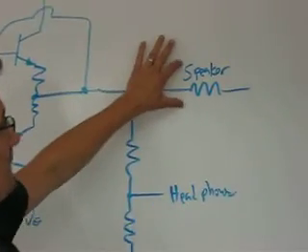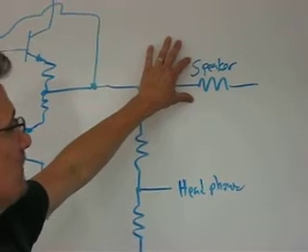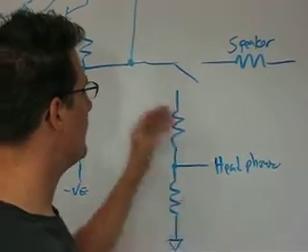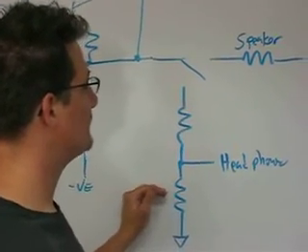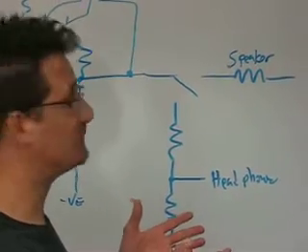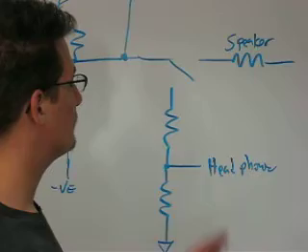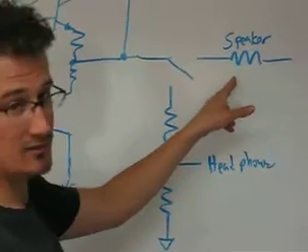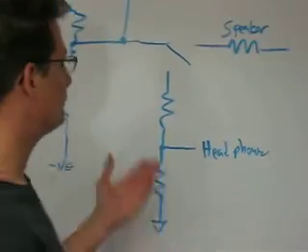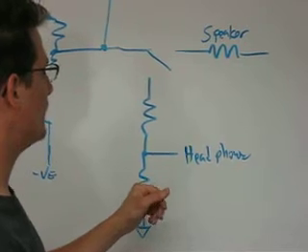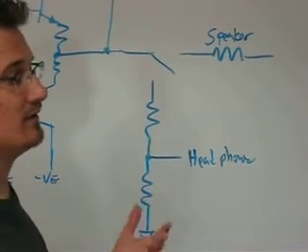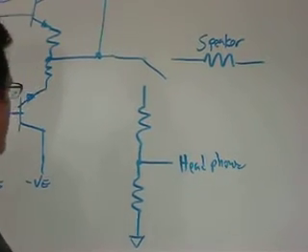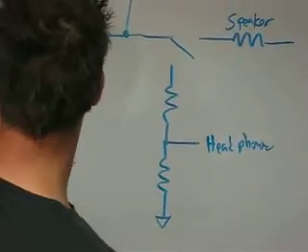This represents the impedance of our speaker. We're using a closed switch audio jack, and then we have this voltage divider network that acts to raise the output impedance of the audio amplifier. So when you put headphones into it, two things happen. A, it disconnects the speaker, and B, sends the audio to the headphones, and raising the output impedance means you don't blow your eardrums or your headphones out. So that's it in a nutshell as far as what this thing does.